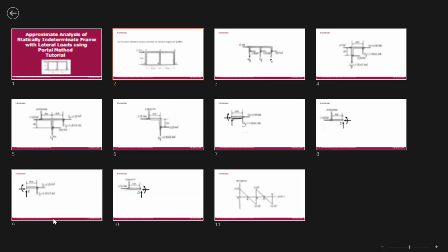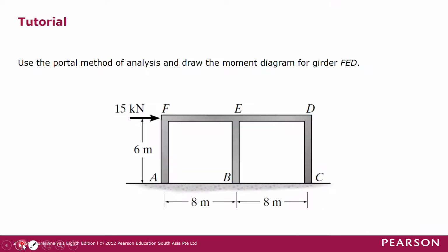So first of all, we have to put hinges at the middle of each segment. These are considered zero moment points or inflection points, or hinges. In this case we need extra markings. So we say this one is A, B, C, D, E, F.